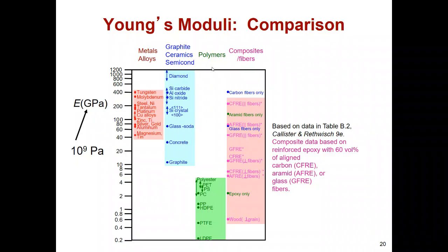However, compared to metal or ceramic structures, a polymer has very weak interaction between the chains. The polymer chain itself has very high strength, since it consists of covalent bonds. However, between the polymer chains there is only very weak van der Waals interaction. Finally, this results in very weak mechanical strength. But polymer structures can be enhanced by adding some fiber structure. We call those structures composite structures.